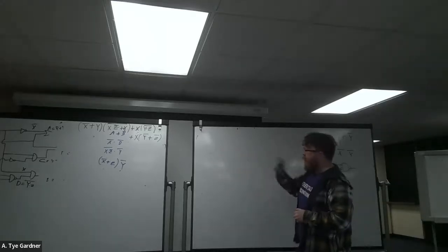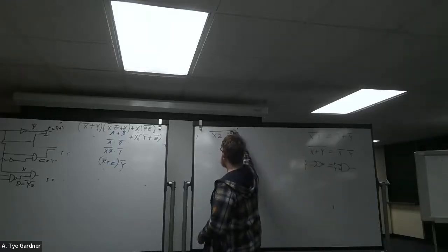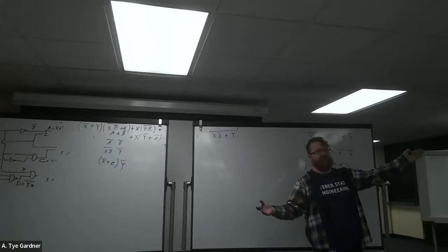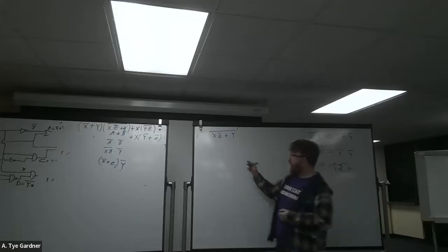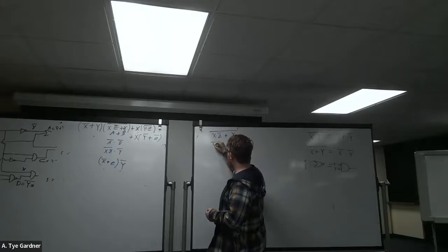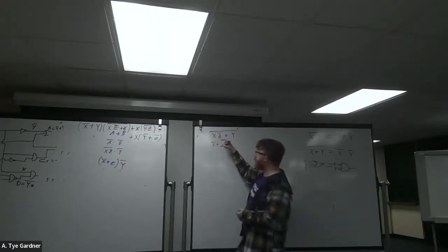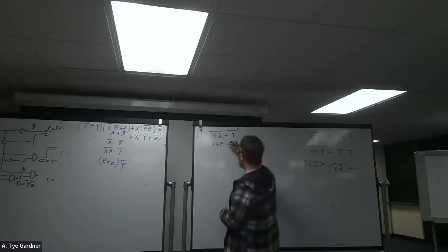Yes. Okay, so let's go the other way, right? Let's just sample this and say X and not Z or Y. Okay, and now we're going to apply De Morgan's to all three gates and all three terms at the same time. Okay, so we get not X because we're flipping, or because this and has to become an or, Z because it's again not Z, and Y.